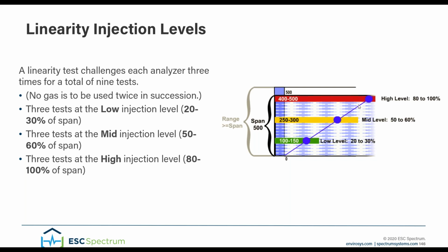Maximum potential concentration during your annual span and range evaluation. All right, that's another good point that Nick brings up. The annual requirement is that you have to do an annual span and range evaluation. And what this does is, in StackVision, you can actually generate a report, and you will pull the parameter that you want to look at, that you're going to do the span and range evaluation on, and it will go over the period of time and show you how many of your readings fall within the 20 to 80% and how many are outside of the 20 to 80%.